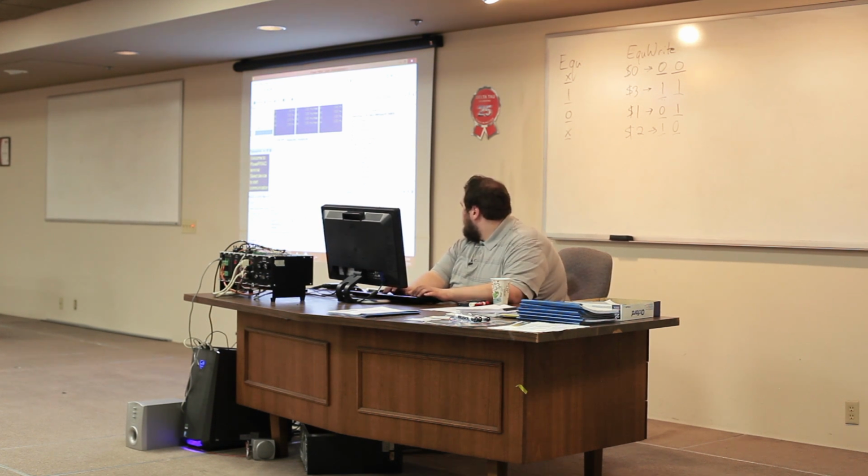So if I issue $1, we see the actual EQU value does not change at all. If I issue $3, it does change. And if you issue any even number at all, it will never change because the forcing bit is still low. But if you issue an odd number, it will set the value.